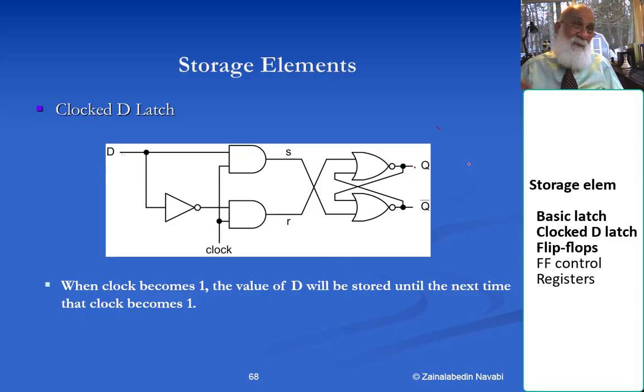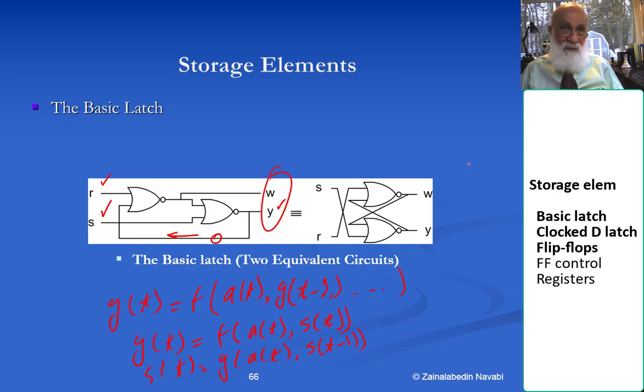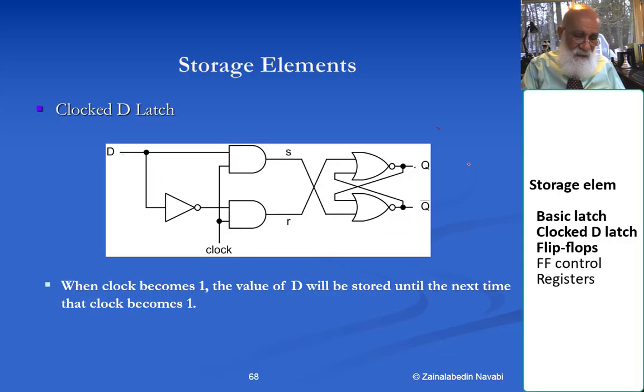Meaning that, for example, I remember from an hour ago that the values of S and R were such and such, or I remember from an hour ago that the S input had a pulse on it. This circuit I showed you here doesn't have that timing component. In order to add that timing component, I'm going to add these two gates to my cross-coupled structure.